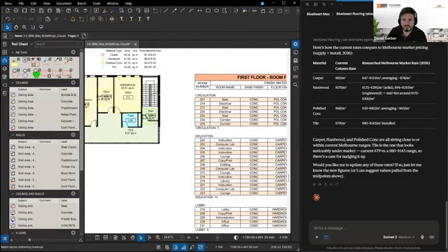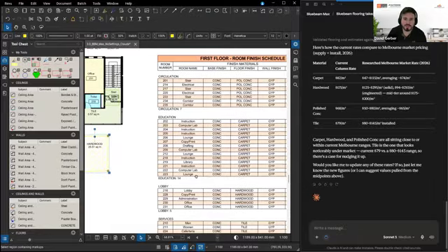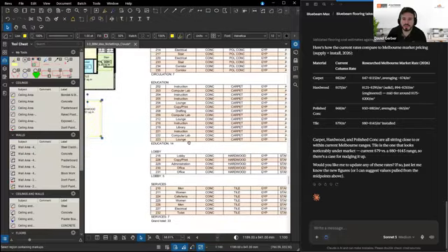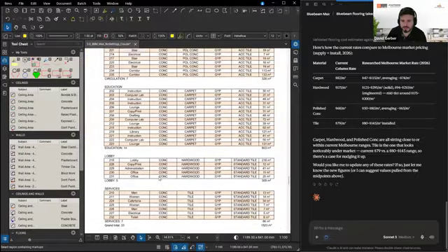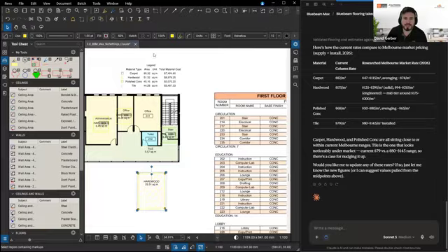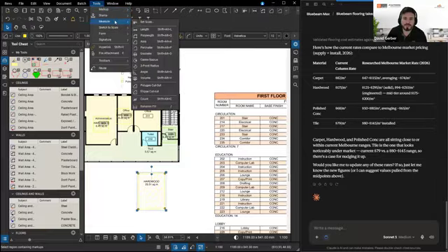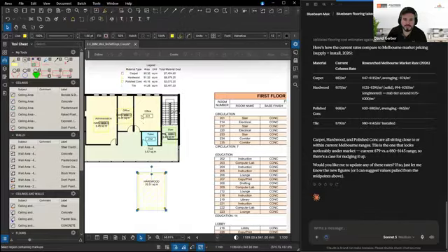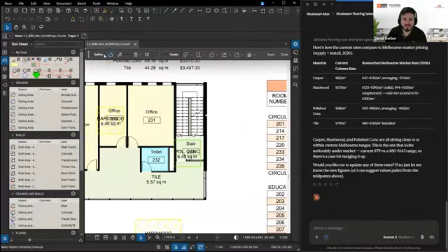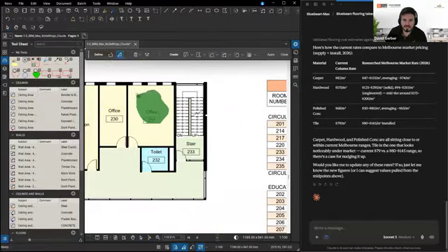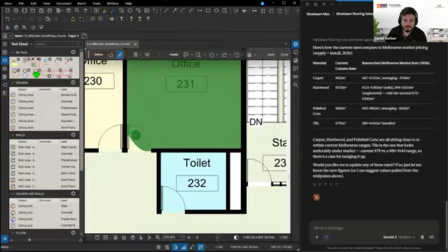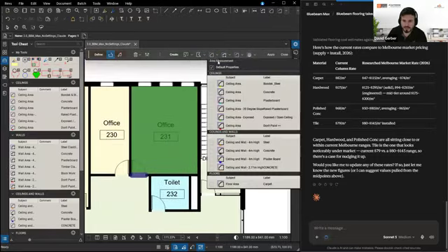So I have a bit more markups in my takeoffs here. Maybe this office, for example, we have our base finish, our floor finish, our wall finish, and ceiling finish. For that office, wherever that is, there's concrete, hardwood, gyp, and then a standard tile. I can start to use my dynamic fill. So it's just J, and then I could scribble into here. Obviously play with the intensity and stuff, so how it finds those edges. You'll see it bleeds a little bit, which I could fix by making a border, making it better than what I'm doing, just to show you. But you can see I have all my stuff here.